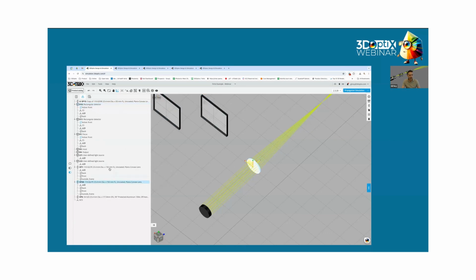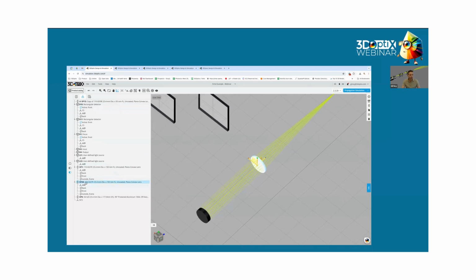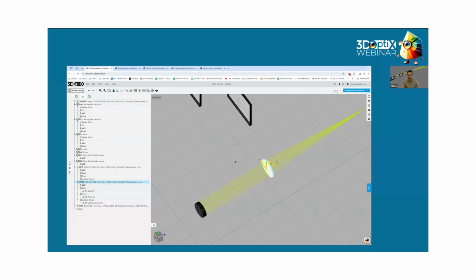Again, let's take the lens, and you can see that it has a few coordinate systems. There is the selected coordinate system. This is the LCS, the local coordinate system, but the lens is composed of a back surface that has its own coordinate system, a front surface that has its own coordinate system, and an outside frame. I can switch between any of those coordinate systems or even add a coordinate system and make just one the local coordinate system. Currently you can see that the local coordinate system, if I select it, is the one associated with the front surface.